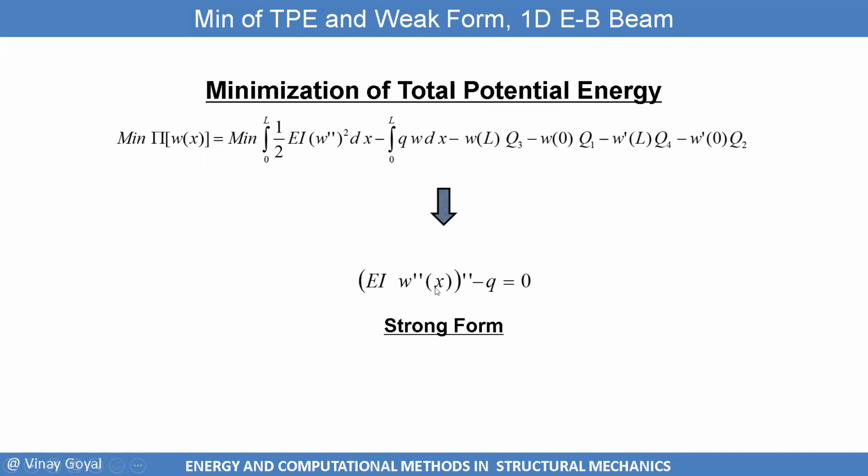And we also discussed the shortcomings in the Euler-Bernoulli beam theory. So, very beautiful, to me it's just an insane idea that calculus of variations, when applied to pi, when I first find the first variation of pi and set that equal to 0, what I actually get is an equation, a partial differential equation. Then the W you solve for is the one that minimizes the functional.